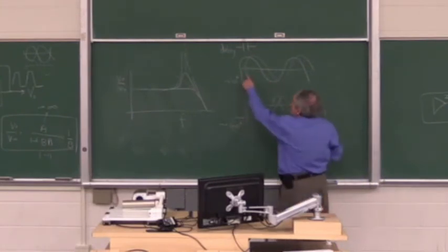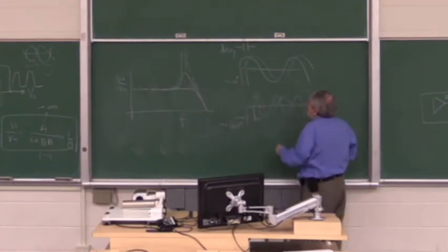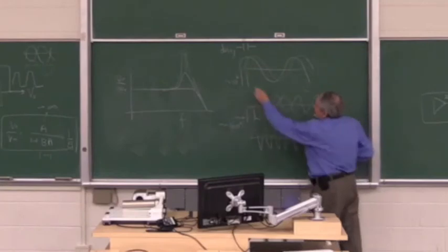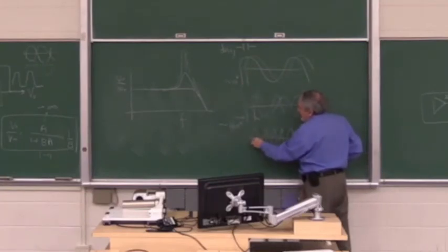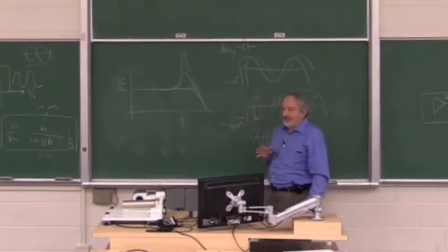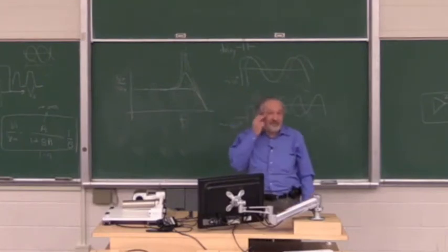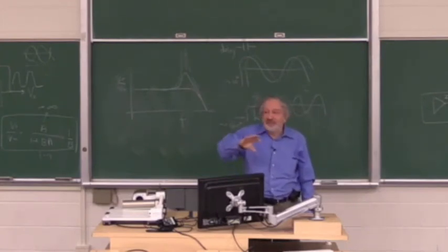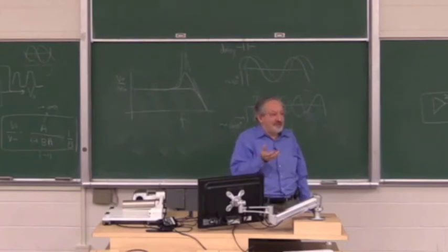Right? If this delay equals half a sine wave, so if I go to a sine wave like this, where this delay is half a sine wave, when I draw it with a delay, it will look like this. It'll have a 180 degree phase shift. Is that clear? So the same delay gives me a bigger and bigger phase shift. So at some frequency, the same fixed delay will actually reverse the phase completely. So the negative feedback will become positive.